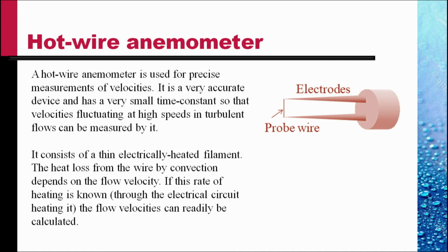It is a device of choice for measuring the turbulence parameters. Its time constant is small because the volume and the mass of the wire, the active element, is very small. So the temperature of this changes very quickly as the flow velocity changes.